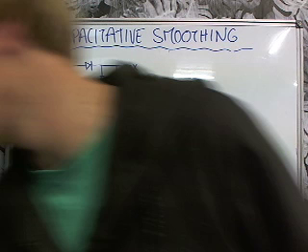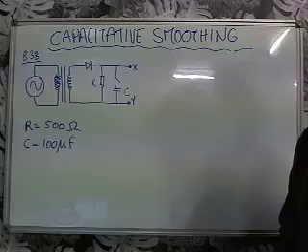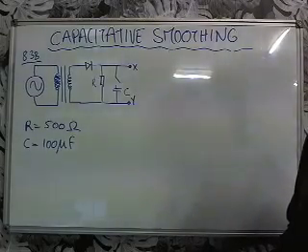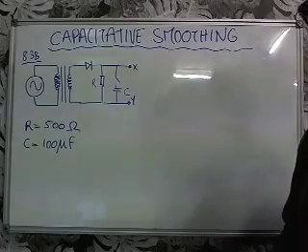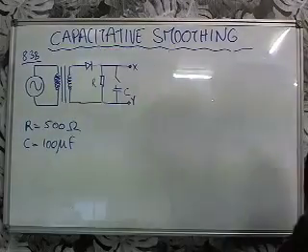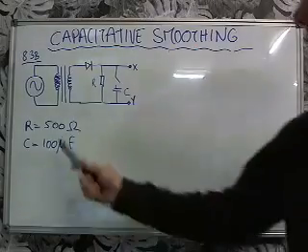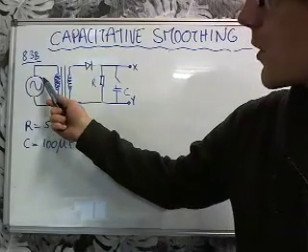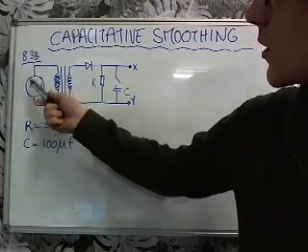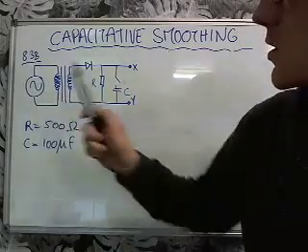Okay, so this is example 8.3b from the textbook, page 304, I think, and they provide us with this circuit diagram. We can just identify quickly the parts of the circuit diagram. This is a sinusoidal, an alternating current source, and we're actually told that that is the mains power supply, so that'll be 240 volts.